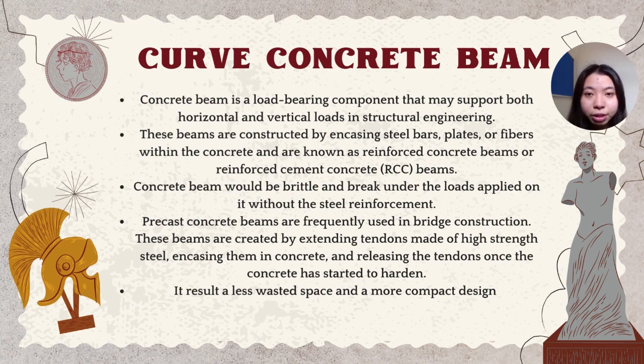The second curved beam is the curved concrete beam. A concrete beam is a load-bearing component that may support both horizontal and vertical loads in structural engineering. These beams are constructed by encasing steel bars, plates, or fiber within the concrete and are known as reinforced concrete beams or reinforced cement concrete beams. A concrete beam would be brittle and break under the loads applied on it without the steel reinforcement.